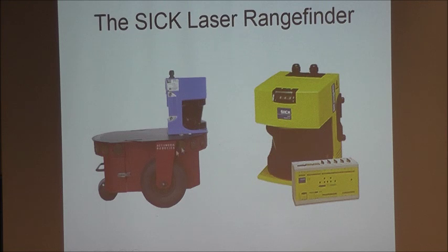Speaking of the Pioneer robot that you see in this chart, we have two of them in the lab, which are not necessarily the latest one, but actually rather old, but they still work. And thanks to my capable students, we have been modifying those robots and bringing them up to current technology without buying a new one. Okay. And now our Pioneer robots have encoders, which measure the velocity of the wheel moving. It has sonar. You see all these, 20 of them. You have 16 sonars, okay, which I'll tell you in a minute how sonar works.